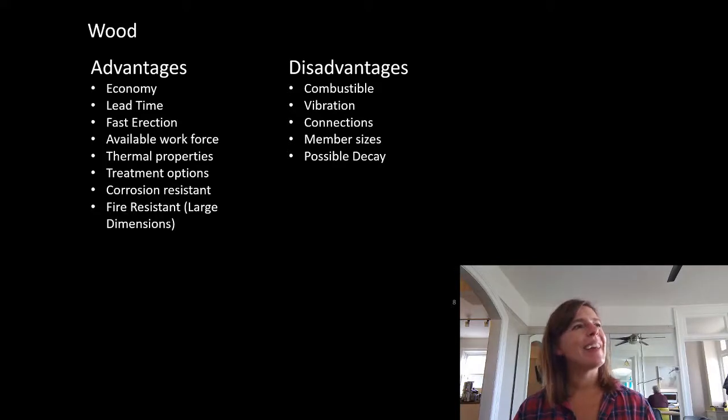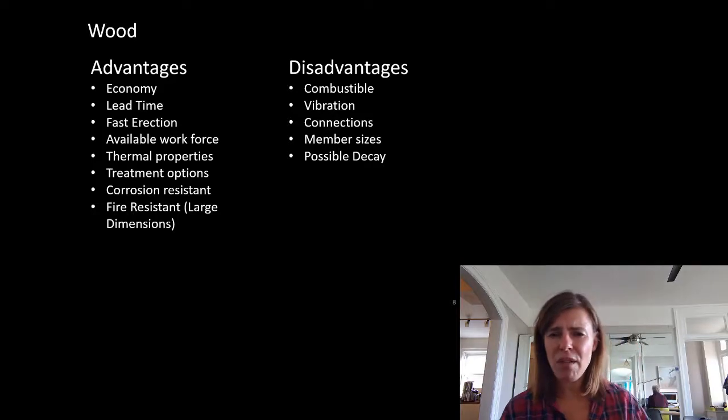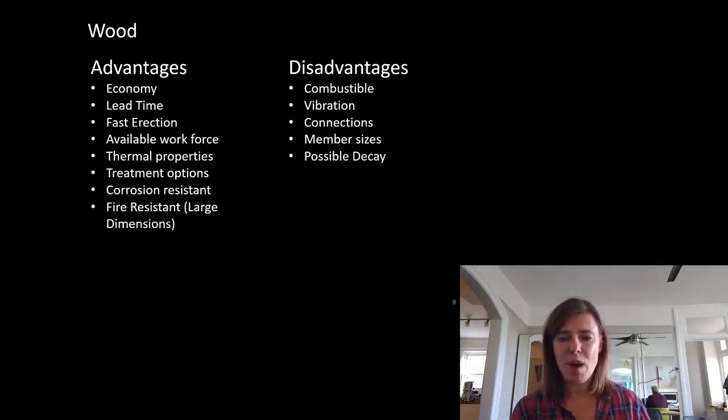I think a 2x6, or like a nominal 2x6, 1.5 inches is what, R2? About R2? R1? R2? Something like that, yeah. Somewhere around R2, which is not nothing. A regular piece of glass is probably R.25, essentially 0. So you have a big building with all kinds of windows.